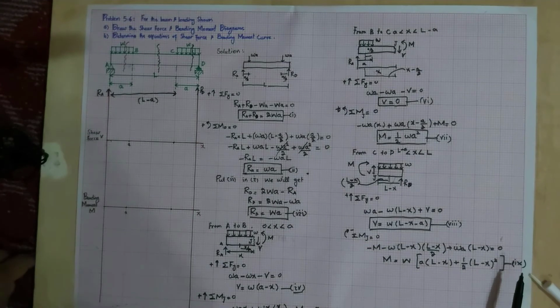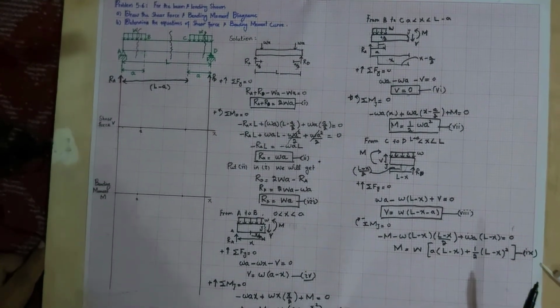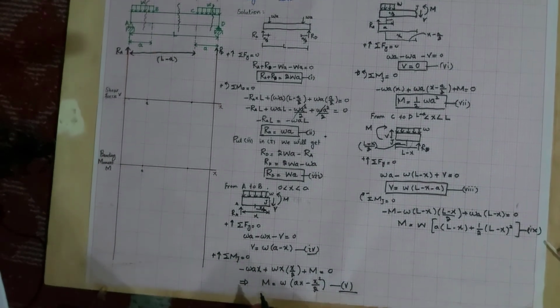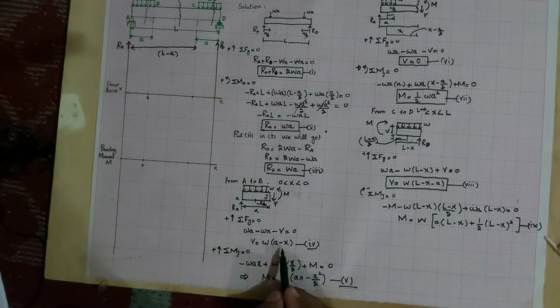Now we will plot these equations in order to find the shear force and bending moment diagram. So first, if you take this equation, if X is equal to 0, we will have V is equal to W into A.